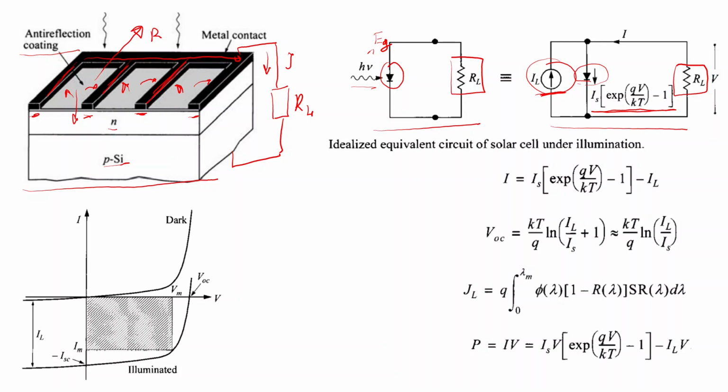That will define the current which flows through this p-n junction based on the voltage drop over the load resistor, which will be equal to the electrical current generated by this solar cell times the load resistance.